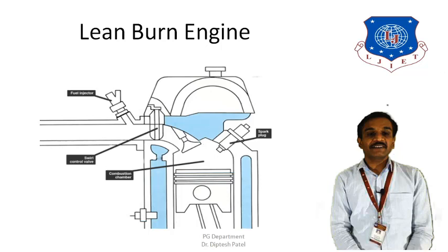So here that is done in the intake manifold before it enters the combustion chamber, and the swirl, which is a kind of turbulence created in the intake manifold, produces a homogeneous mixture of air and fuel. You can see that the injectors are attached to the intake manifold where the air fuel mixture is created, and afterward the swirl control valves, which control the swirl of the air fuel mixture, are installed, and then it enters the combustion chamber through the intake valve.